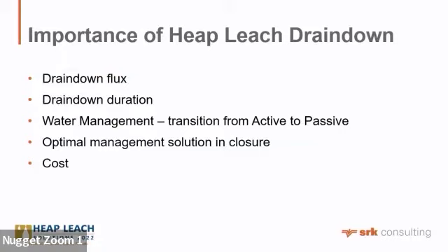It's important to know the drain down flux and the timing of that flux, the duration of the various levels of flux, if you wish, so that ultimately we can design water management schemes that can take us from active water management, in this case pumping, to a passive water management, which could be no pumping, or in some instances a semi-active scheme where you need to do some water treatment but you don't need to recirculate.